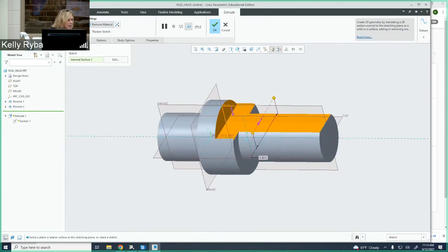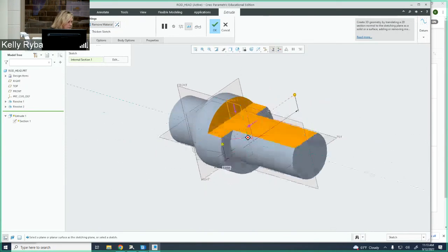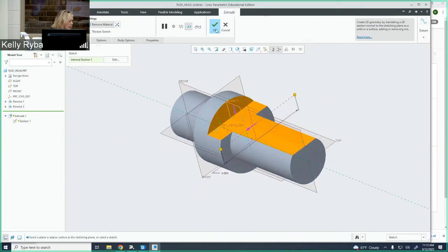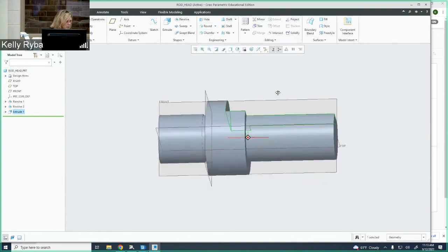I need this to be wide enough so that it's not going to leave little bits. So since that collar width is 2.125, I'm going to say 3 is going to be my number, okay? And it's very generous beyond, okay? Very generous beyond. So I can say, okay, I wish we could do a symmetrical through all, but it doesn't have that. It doesn't have that second level. It's kind of like 2 in 1. There we go. There's our cutout.